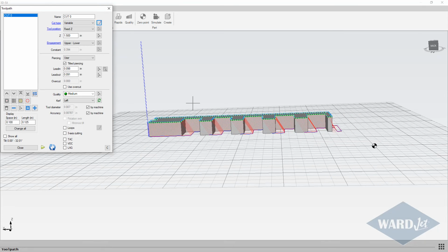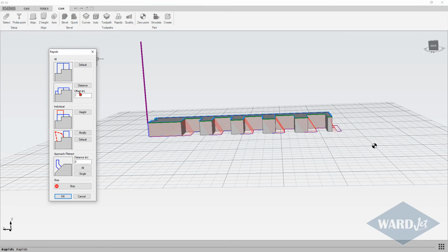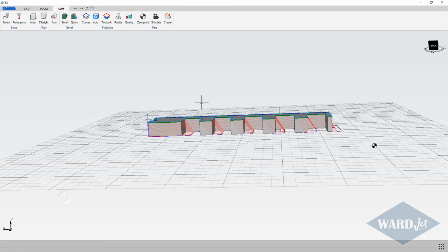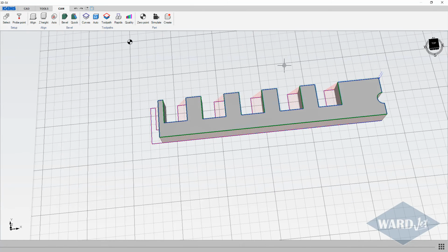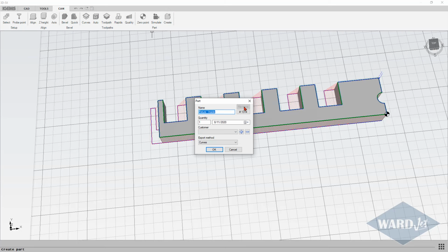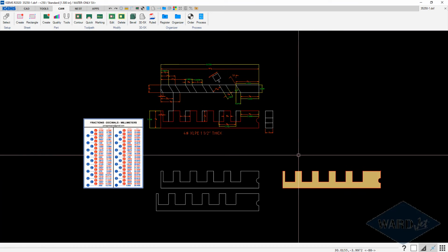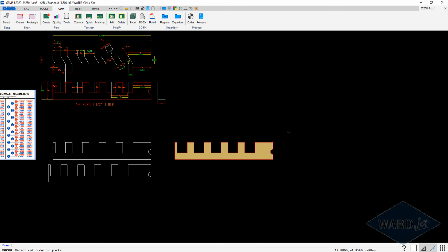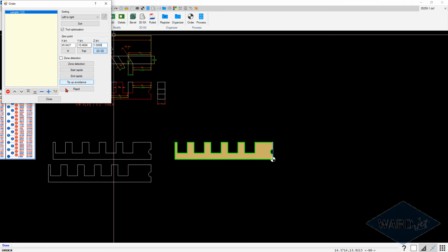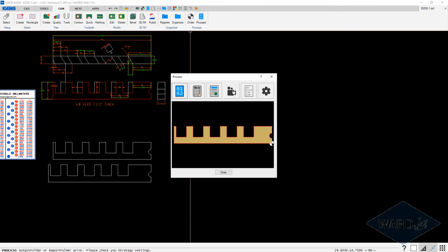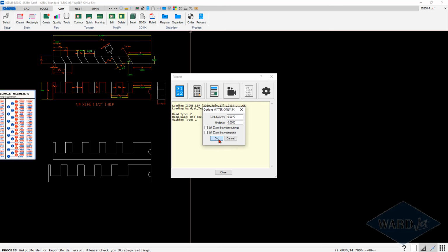So that looks good. Then we just need to set our lift between the cuts there and set our 0 point. So if I spin this around here, set my 0 point wherever I want on the part. If I'm just doing a single part, create it, and so on. And then of course once you have it out to this point, if you're just doing the single parts, set your order button, click on the part button, make sure the Z is 1.5, process, and we can do our simulation in here also.